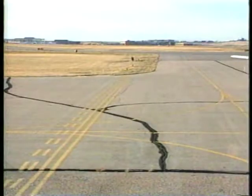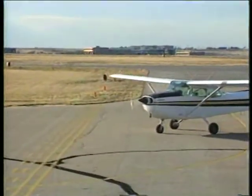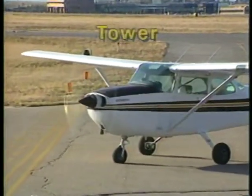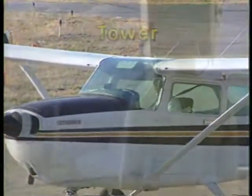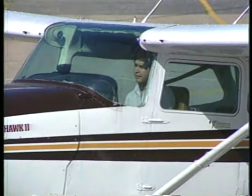Once the pre-takeoff checklist is complete and you're ready to depart, taxi up to the holding line, switch from the ground control to the tower frequency, and let the tower controller know that you are ready to take off. Be sure to give your direction of flight or destination. Sudden tower, Cessna 62740, 17 left, ready for takeoff, VFR southeastbound.